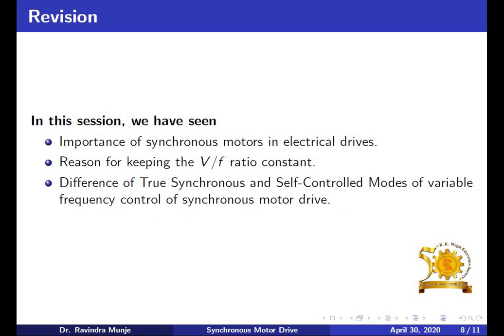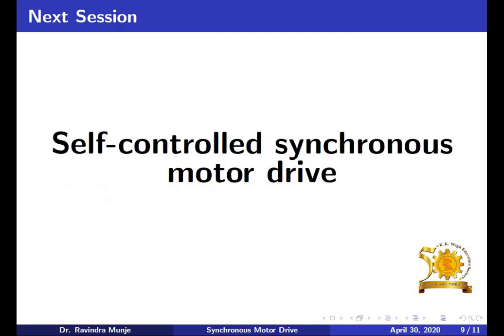So whatever we have seen in this short session is the importance of synchronous motors in electrical drives, why there is a need to keep V by F ratio constant for below base speed operation, and what is the difference between true synchronous and self-control mode of variable frequency control of a synchronous motor drive. These topics we have discussed in this session. Next session we will talk about the self-controlled synchronous motor drive. Thank you very much.